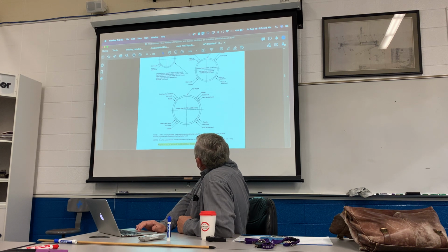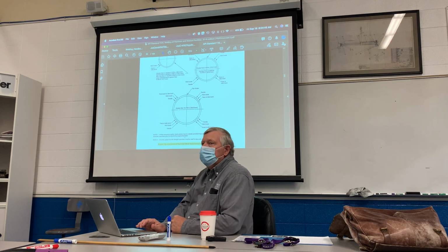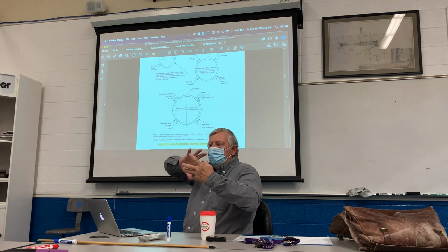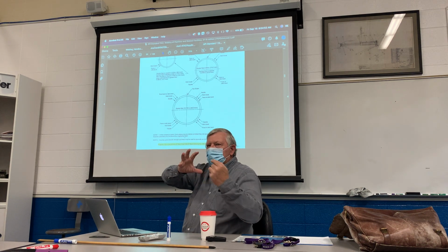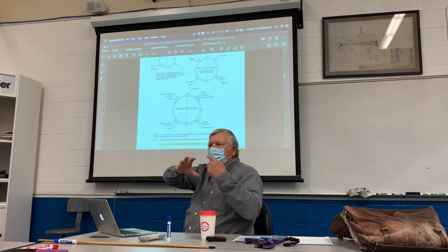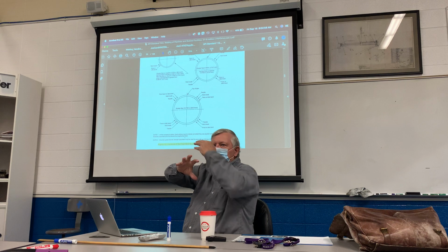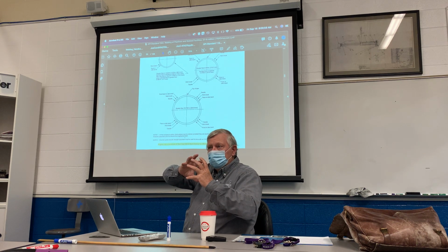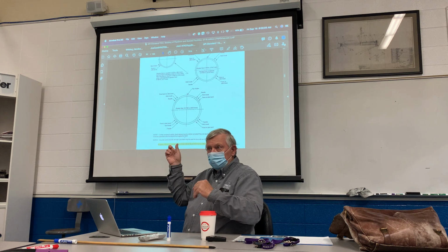Notice here under note 1, at the company's option, the locations may be rotated provided they are equally spaced around the pipe. However, specimens do not include the longitudinal weld. And that's why you get that rotation rule in there, because sometimes welders will turn the pipe. So you have a piece of the seam weld here and a piece of the seam weld here. You're not ever supposed to put them in line, but you can put them in line on a welder qualification test because of this rule.